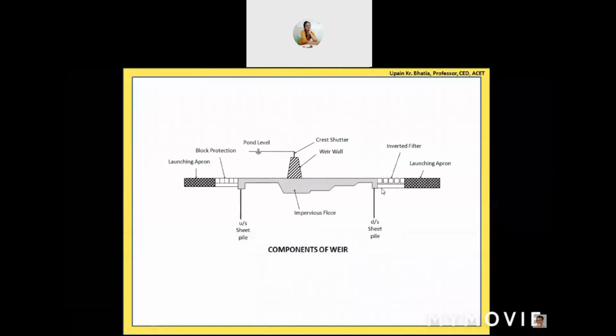That means as you move from bottom to top, the size of the particles keeps increasing. So the permeability increases from the bottom part of this layer to the top part of it. And in these gaps, we fill the bajri, or you can say the aggregate. Those aggregates are put into these gaps so that these gaps are maintained also, and the water can come out easily from this portion.